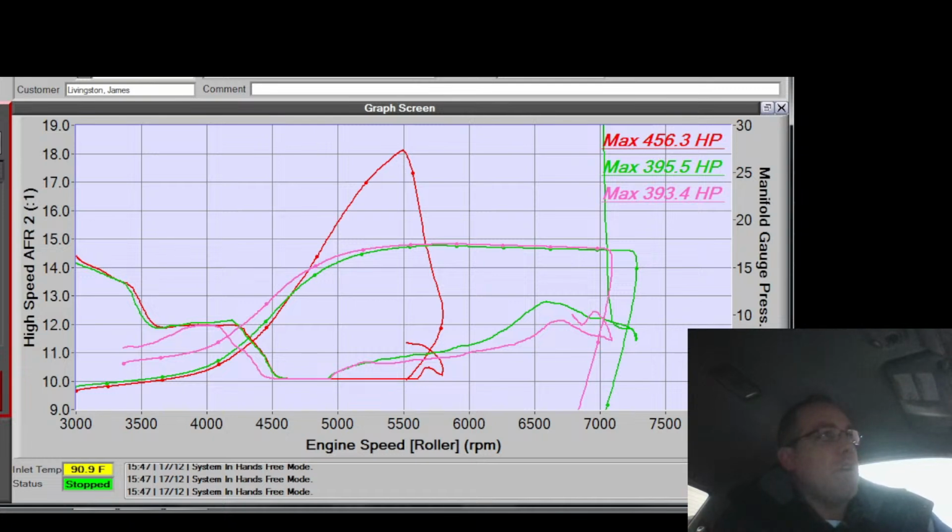Yeah, pressure. So the speed at which MAF is measured depends greatly on the system. If you've got a big front mount, you have a big accumulator in front of the throttle body before it even gets to the MAF. So if you're on a front mount, you're definitely going to see pressure before MAF. If it's on a top mount in a stock type setup, the MAF is really quick, and the pressure's fast too. They're both pretty quick. But you don't get a choice, right? You don't get the choice of what the ECU uses for those.